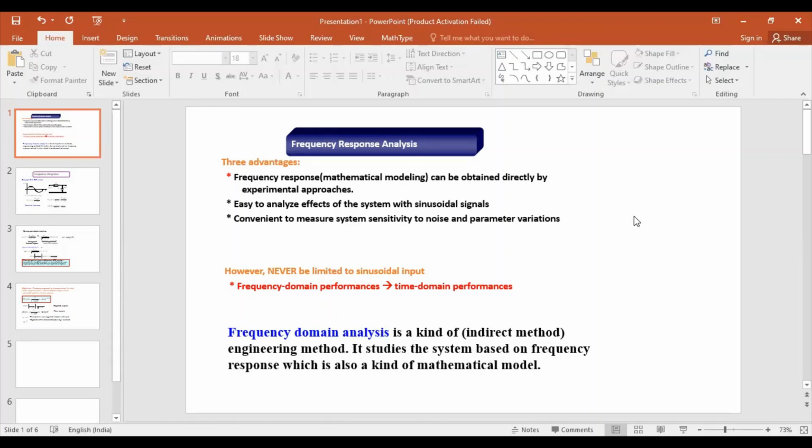Fine. I repeat, you have done an experiment on an RLC circuit, you applied a sinusoidal input, keeping the amplitude or the magnitude of the signal constant, but varied the frequency from say 10 hertz, 20 hertz, 30 hertz, 40 hertz, like that. At a particular frequency, we encounter resonance in the circuit, at which there was a maximum current. How did you come to know that there is a maximum current? One way is by connecting a voltmeter across the resistance. Whenever you reach a maximum voltage drop across the resistance, it indicates that there is a maximum current in the circuit.